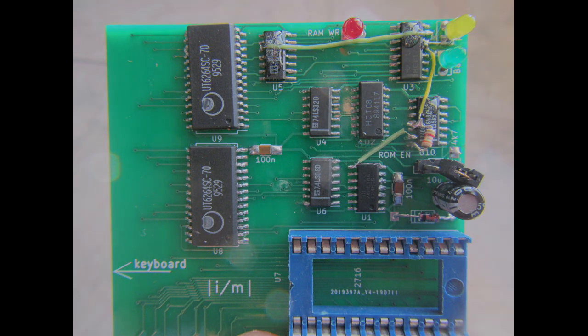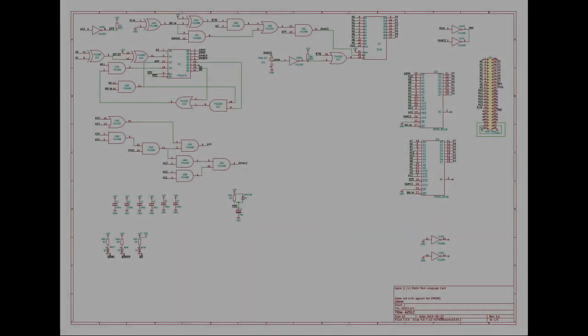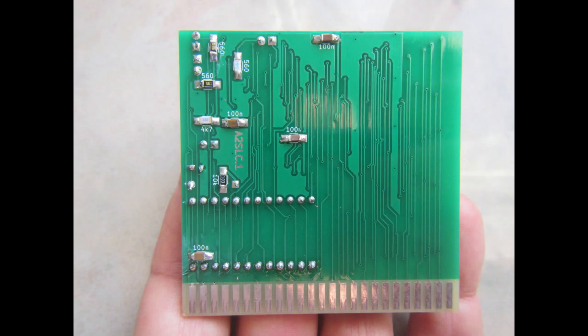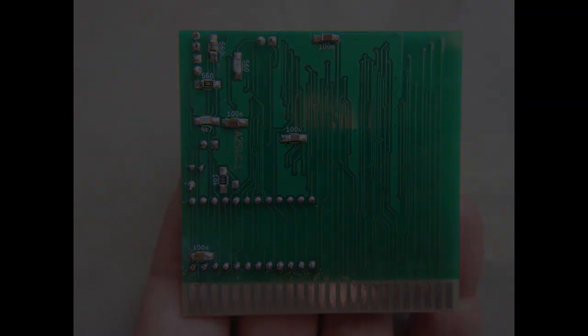I mostly used CMOS gates from the 74HCT family, but also used real 74LS gates, and you don't really want to pull down an input of a real TTL gate. I mean, of course, it's perfectly fine to tie an input to ground, but if you want to drive an input high with a pull down with another gate, you cannot really do that with another LS gate.